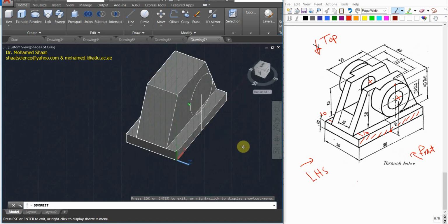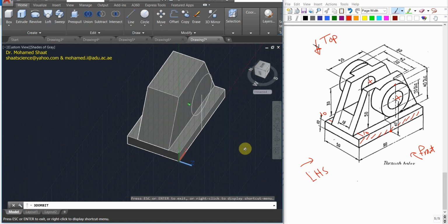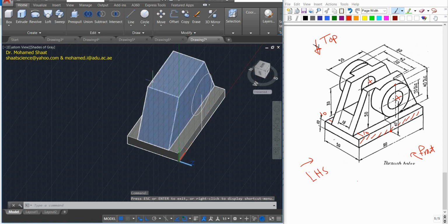Now you can have one of two options: either align this center, move it back to the mid plane and extrude to the right and to the left 30 and 30, or you can move it to this face and extrude back 45 and to the front with 5. It's up to you. Okay, but the question is, how can we move it back?